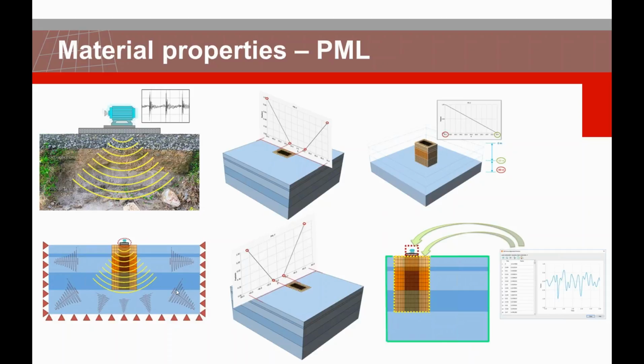What is important here is the incorporation of the spatial functions that you can define in conjunction with PML based on different directions that you have in the model. Imagine if this is your X, your Y, and Z, you need to define a special function, 0, 1, where 0 means no absorption and 1 means full absorption towards the boundary. So this is very important.